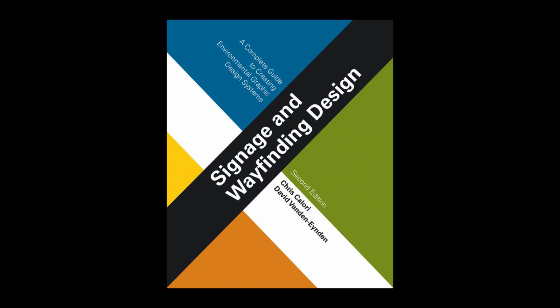These activities include coordination meetings, submittal review, shop visits, site visits, and post-installation punch list inspections. At the very least, the designer should be thoroughly engaged in submittal review and approval, providing review comments and acceptance status marked up on the submittals. The designer's involvement is also key to more effective coordination meetings, shop and site visits, and punch list inspections. Depending on the project, the designer may also be involved in providing coordination memos and meeting notes.